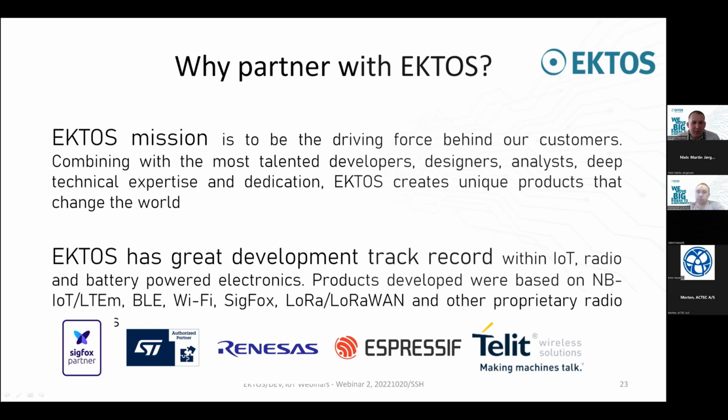Okay, good. Thank you for your question. Actually, we have some good experience with Espressif modules and SoCs. The thing is that somehow they are not designed for battery-powered applications. They consume a huge amount of energy compared to other vendors. And we would not recommend using them for applications with BLE and Wi-Fi.